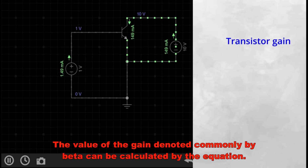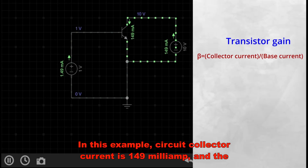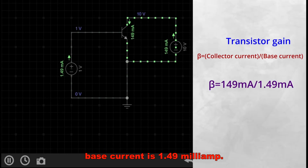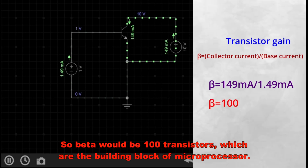The value of the gain, denoted commonly by beta, can be calculated by the equation beta is equal to collector current over base current. In this example circuit, collector current is 149 mA and the base current is 1.49 mA. So beta would be 100.